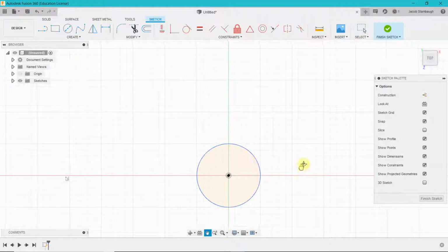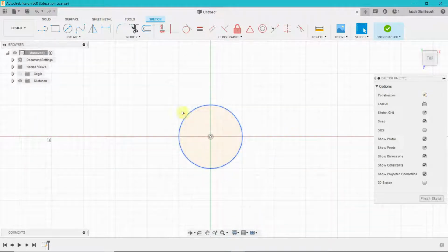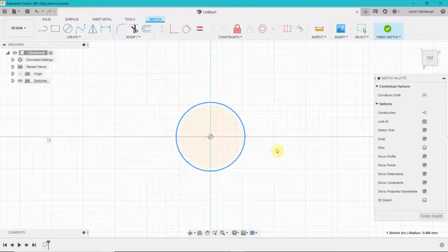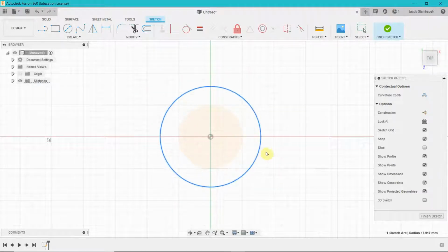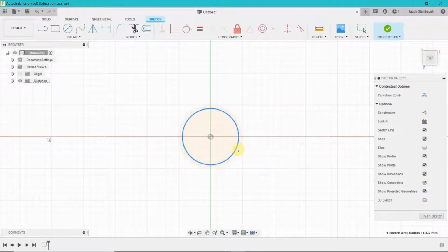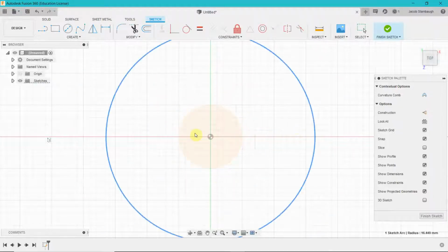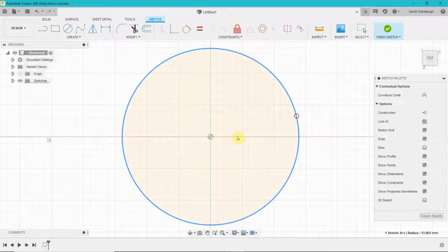One important thing with sketching is that when it was 10, it was black, but now it's blue. This is what we call defining a sketch in CADing. When you fully define a sketch, you won't be able to click and drag it like I'm doing here. In this case, it's not fully defined, which means there is no definition for how big the circle can be. The only definition we have is that it has to start at the origin.